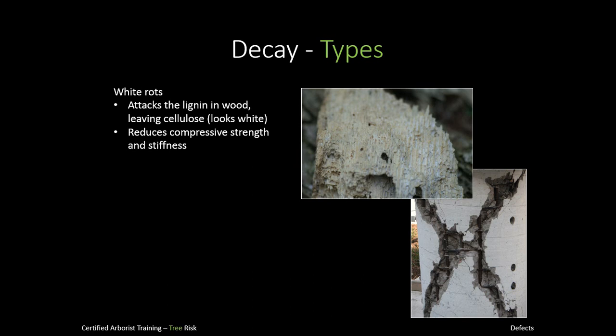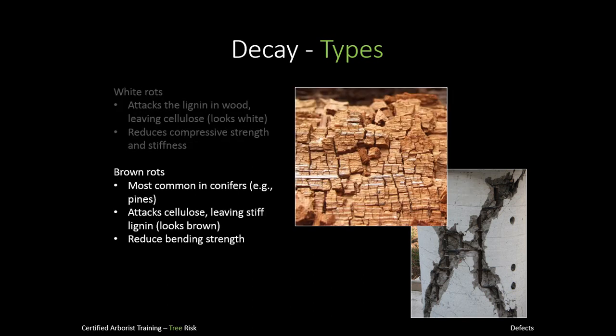The rebar, if you just had a roll of rebar and you put a lot of weight on it, eventually it would just crumple and bend and flatten out, right? With the concrete there, it's very stiff and resists a lot of compression. But the rebar is what makes the concrete stronger when you have bending strength.